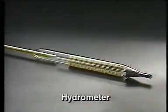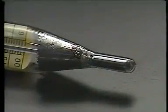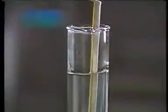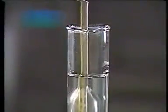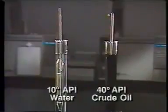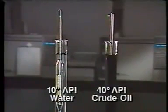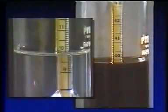You may have used a hydrometer to check your car's battery fluid. It's usually made of glass with lead shot at the bottom. The hydrometer is placed in the liquid being measured. The liquid will have a buoyant or upward force on the hydrometer. Just as a boat floats higher in salt water than in fresh, a hydrometer will float higher in a denser liquid. This means that the reading will be a lower number on the scale.